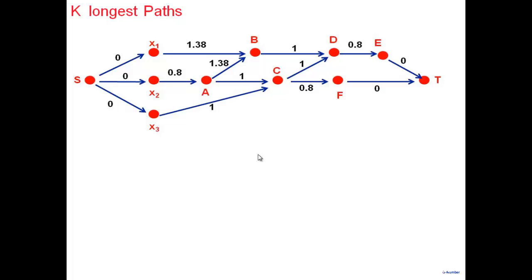So I've been showing you a library of gates. At various points of time, I showed you that this is from a 180 nanometer library. So I have elementary gates, elementary blocks whose design has already been done right to the layout level. So the elementary designs have all been done beforehand, and layout has been done and the delays have been characterized. So I have all the delays of my gates. So those delays are what I'm putting here.